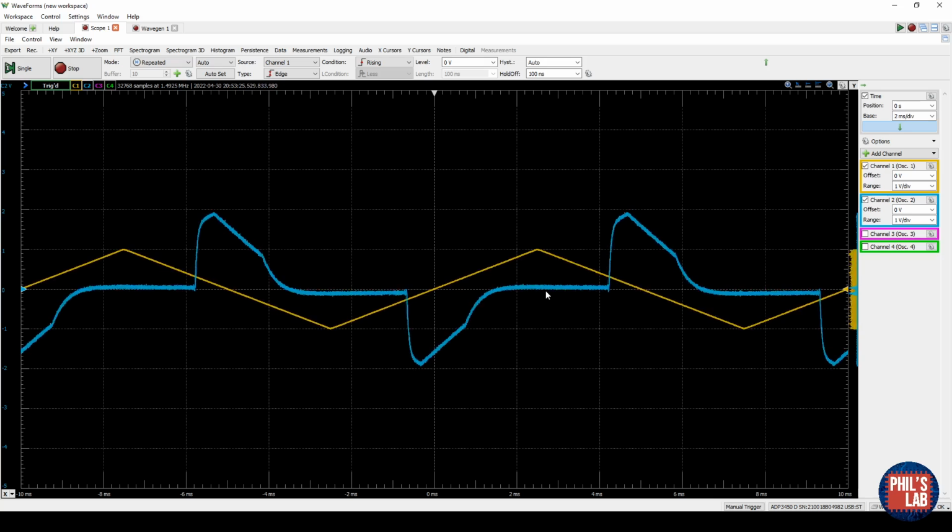I've set a certain threshold, which seems to be around midway of this input wave. So below that, our noise gate essentially clamps, and we get 0 at the output. Then you can see this fast exponential over here is our release filter working. So this is 10 times faster than our attack filter. So we're releasing very quickly, so as soon as the input signal goes over the threshold again, we can go back and pass this signal very quickly. So we get the peak of our triangle wave at the output over here.